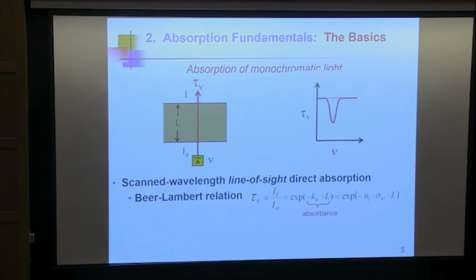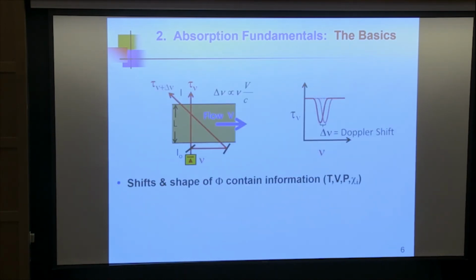The Beer-Lambert law applies whenever it's monochromatic light, whether it's a small molecule or, here, a big molecule, where we do this with a cross-section. If it's a small molecule, we think about line strengths and shapes, mole fractions. If it's velocity, we simply angle one of the beams through, and we can see the shift in the absorption line position. This is the shift in the wavelength of the laser needed to absorb light for that moving gas. As I mentioned, we've done this for velocities as low as a few meters per second and as high as 15 kilometers per second.